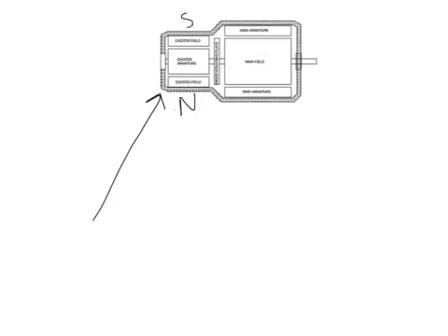So when we turn the exciter armature, which is right here, through the field using a mechanical force, it's going to cut across the north and the south pole, which in turn will generate a voltage causing current to flow.